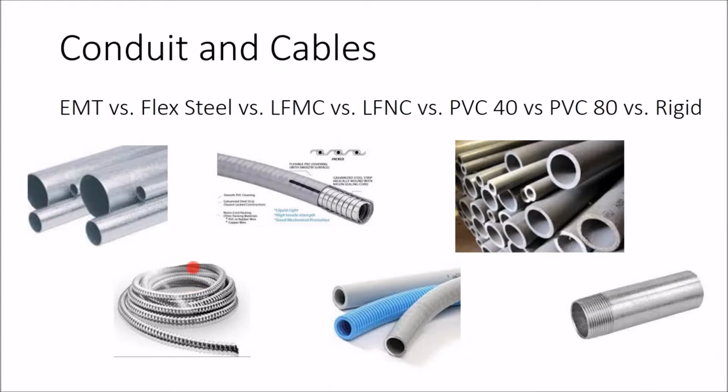You may have a metal conduit with no plastic liner, and that could be fine for indoor applications. But if you're going into wet, damp, dry, or sunlit environments, you might need additional weather protection. In my mind, it simplifies when you think: the metal is for physical protection, and DC has to be physically protected that way. Plastic is more for being weatherproof, and there are combinations, like flexible conduit with metal and plastic. But that starts to get costly. You might use this for short conduit bends or transitioning from outdoors to indoors, and once you get inside, you might transition into more indoor-rated material, which is a little cheaper but also a little less weatherproof.